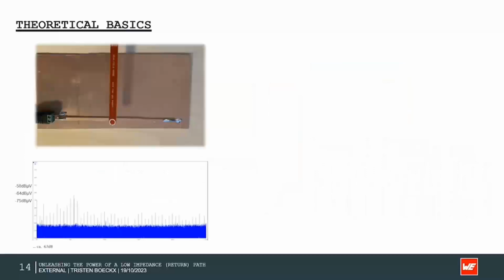If we start measuring at the edge on the top, we will see no signal. We will measure no signal from the signal trace. When approaching the signal or a transmission line, we will be able to detect the return current as shown below in the left bottom picture.